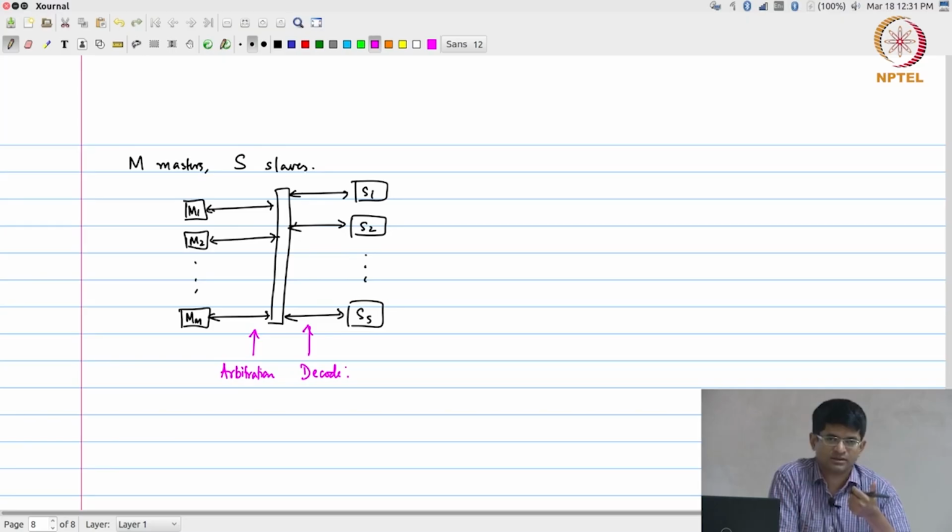DMA, on the other hand. So what is DMA? It's direct memory access. We will look at that a little bit more, especially in the context of actually implementing the hardware later. Direct memory access is specifically introduced to do one thing, which basically says there can be situations where I just want to copy a large amount of data from somewhere to somewhere else, from some bunch of memory locations to another bunch of memory locations. It's possible that both of those blocks of memory are in the actual RAM itself, or one block could be in the RAM and the other one could correspond, let us say, to the Ethernet device, or it could correspond to the video display.